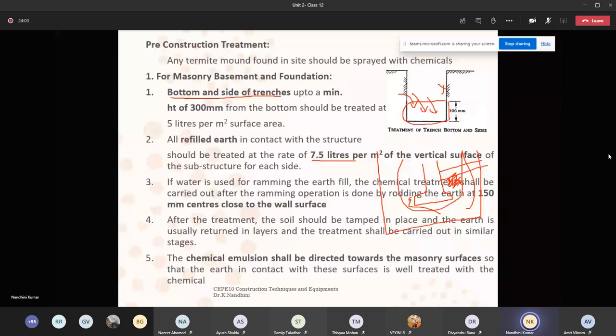Once it is done, over that you will use your 40 mm gravel. Over that you will lay your cement mortar. Finally, your cement slurry will be done. Over that only you will place your carpet materials, that may be brick, mosaic, marble or tiles.